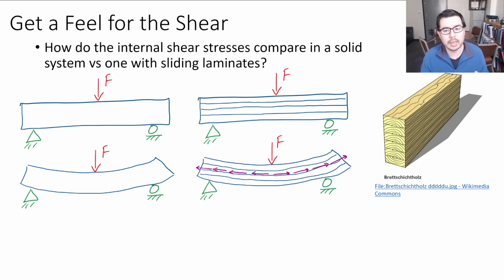Another thing to keep in mind, which we'll derive but is not necessarily obvious right now, is that this transverse shear stress, which acts along the longitudinal direction, orthogonal to the direction of the load P, or the vertical direction, actually gets smaller as we get farther from the neutral axis.